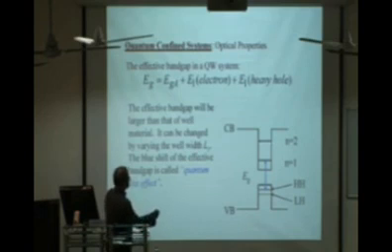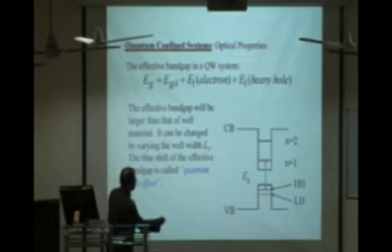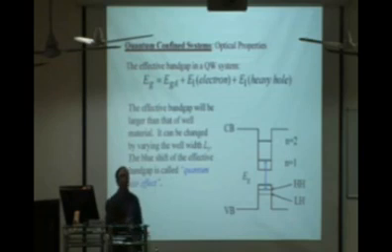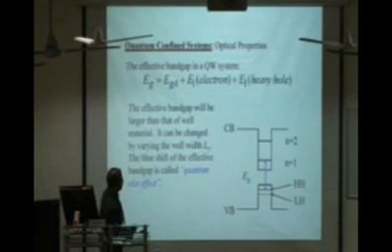And as you see, this is the ground state energy for the electron, and this is the ground state energy for the hole. In fact, the valence band is more complicated. You have heavy holes, light holes, and spin-orbit split holes. So a lot of complicated things are there. But we take the heavy hole, as it probably has the lowest energy, so that is the ground state energy. Initially we started with a semiconductor with a band gap Eg, and because of the quantization, the band gap has gone up like this.